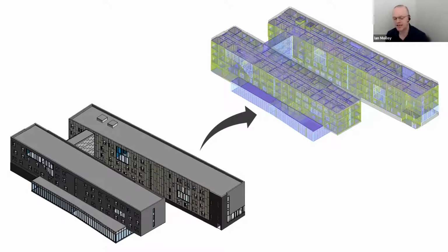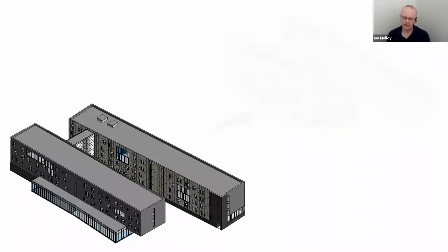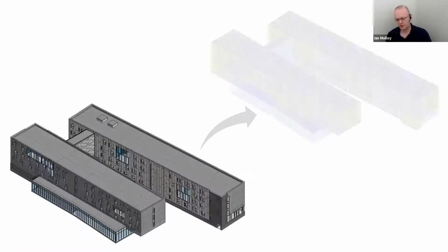And here, what you'll actually see is every individual space has been taken off. It's normal practice in energy modeling to group a lot of spaces that are on the same zone or thermostat or the same usage and things like that. And that's perfectly fine. In fact, in many ways, this level of detail is not even required. Yet it's what a lot of people try to achieve, thinking that this is what they must do to achieve an accurate energy model. When in fact, that's not actually great. Something like this is probably better, somewhere in between.